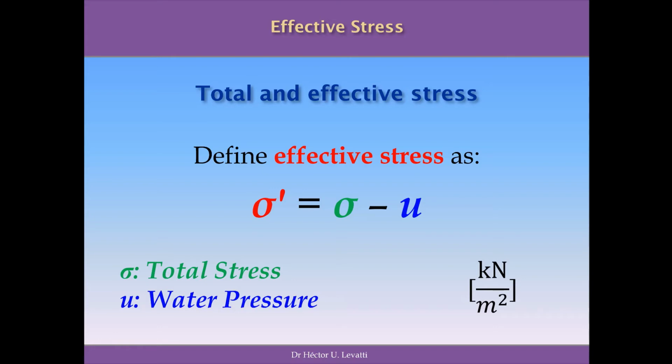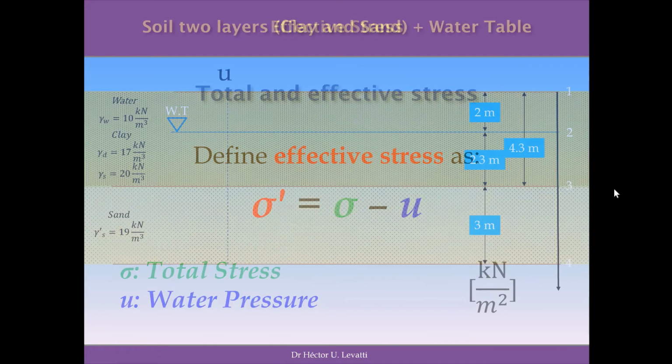For unsaturated soil, there are equivalent expressions of the effective stress, but they are sometimes not accurate, because this concept works pretty well in saturated soil, but in unsaturated soil we are still doing research in order to find the definite relationship, a sort of effective stress that works for every problem. But let's consider we are in the world of saturated soils, so we are going to use this principle to show how to evaluate the effective stress in a practical case.